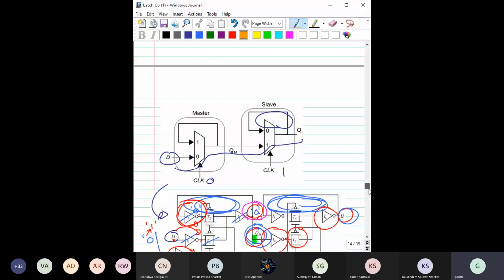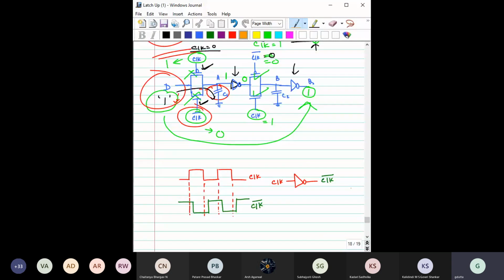That is for the static case, master slave, right? Here, how many transistors? 1, 2, 3, 4, 5, 6, 7, 8. Right? So the total number of transistors required is significantly lower for the dynamic register compared to that of the static register, right? So that is obviously an advantage. More transistors means more area, right? More delay, more power dissipation.